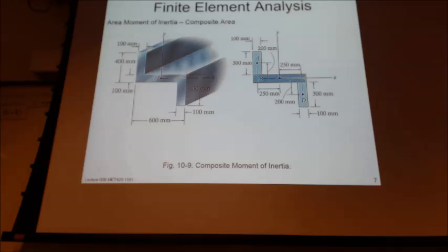Okay, and we use those area moments to combine and determine the composite moment of inertia for a composite shape. So for rectangle B, we can just take the area moment. For rectangles A and D, we're going to have to apply what? Parallel axis. The parallel axis theorem, right? So you'll sum those all together and you can obtain the moments about the x and the y axis.